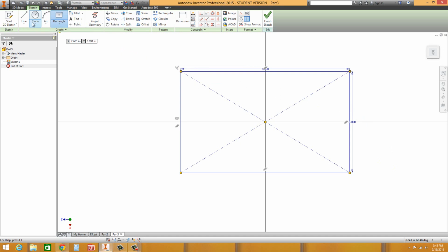Okay, now you could add the circles here. You could add them individually, like just click on the circle tool, and do not, whatever you do, stay away from this center line or any of these center lines. Those don't help you right now. You want to make sure you draw away from those. Click. Don't even snap this to it, because look at that, it gets a tangent relationship. Stay away from that. And this is supposed to be 0.5.